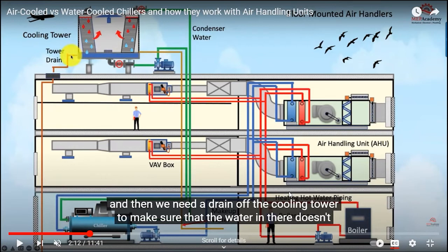on the top of the building. Cooling towers, I told you, are something that refrigerates water, or cools down water, for free. But the setback is that we have to use water. We have to use water. Okay, so you can see that this is not a closed circuit. If you follow this pipe, it ends at the top of the cooling tower, and then it releases water. Okay, so it's basically we have a coil. So how does it work?